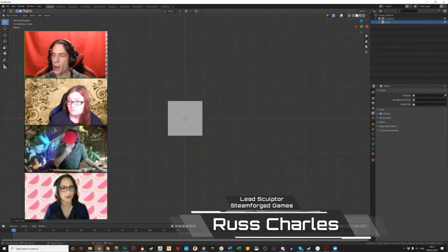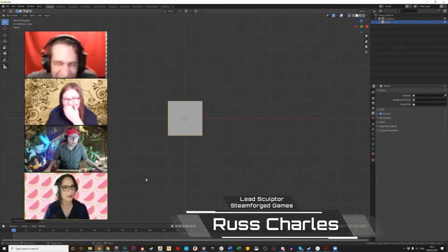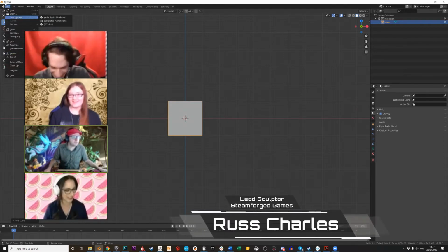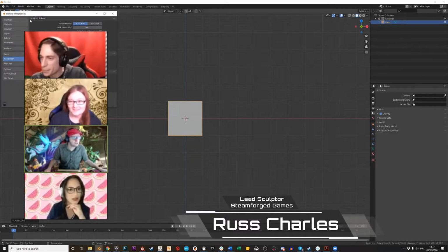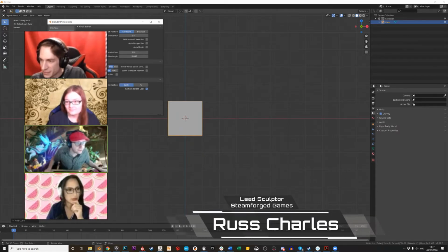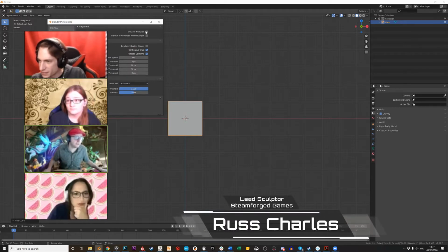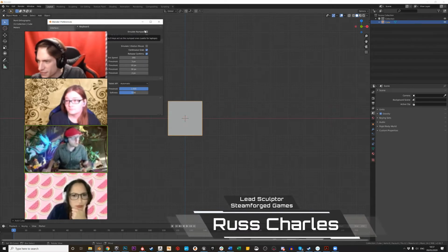Okay. I'm on a Mac and none of these hotkeys are doing anything. Yeah, I think I made a mistake doing this on a Mac. I should have probably done this on PC. You're absolutely fine. If you go into Edit and go to Preferences, there is in here, I just need to remember where it is because I very rarely need it. Yeah. There we go. Under Input, there is an Emulate Number Pad, and if you tick it, you'll find that the top row keys on the keyboard will also work for navigation.